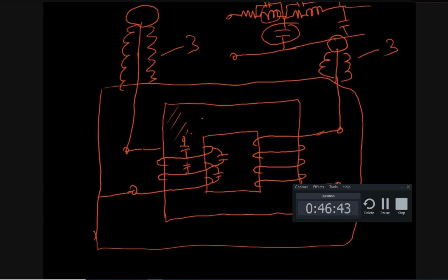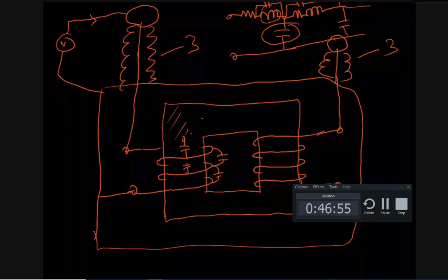Please listen, I am not opening the transformer. What I will do is conduct a test at this terminal using a voltage source, say V, and then like this. So it is actually a complicated one. I am explaining very simply so that you will understand. So here a voltage source I am connecting. This is an offline test, not live.